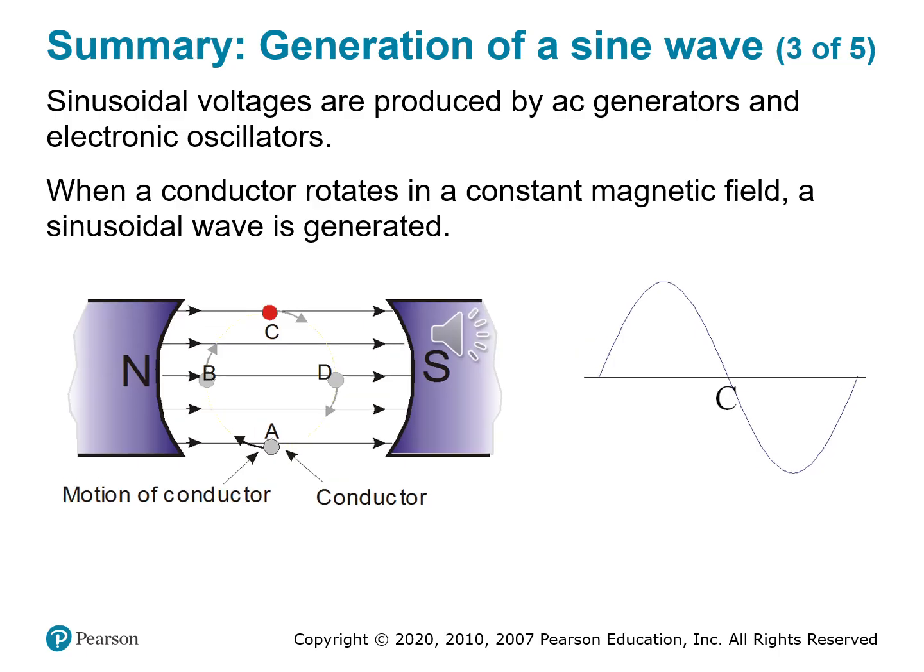Okay, let's look at the wave as it crosses zero, the midpoint of the cycle. Again, we're halfway through our rotation and our conductor has reached point C, the very top of the circular path. So what happens here? Well, just like at point A, the motion of the conductor is once again parallel to the magnetic field lines. That means it's not cutting across them, and therefore no voltage is induced.